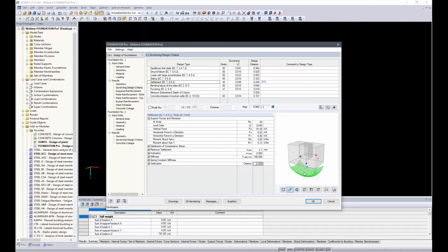This looks like the module is doing the calculation using a flexible foundation slab, but if you see this message 211, this means the calculated plate stiffness is greater than 1.0. The plate is solid. The calculation as a solid plate is of course also possible.